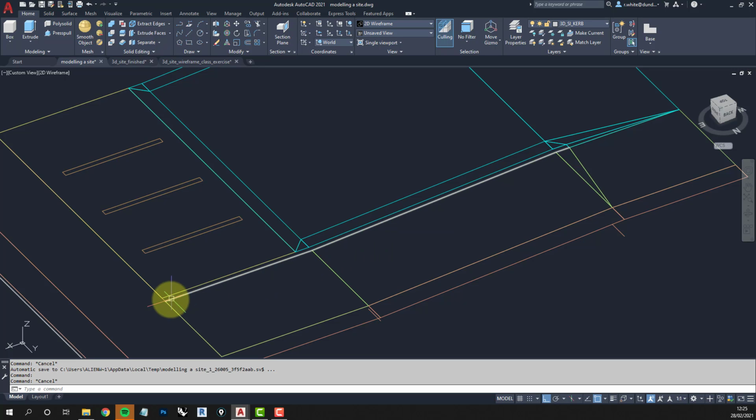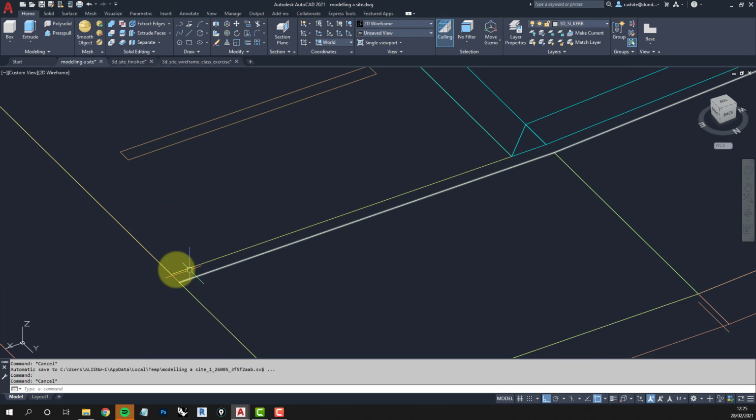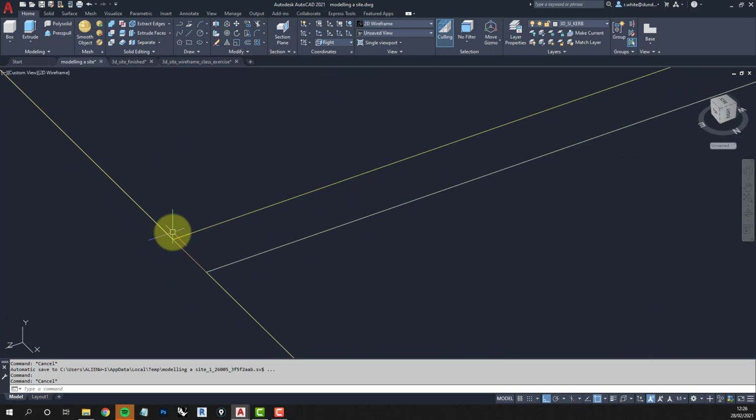Now we need the object that's going to go along that path. So we need to change to the front coordinate system now. Sorry, the right coordinate system. It's got the right coordinate system, so we're working at the end of the shape. We said it was 150 millimeters high, so I'm just going to draw a line up 150.